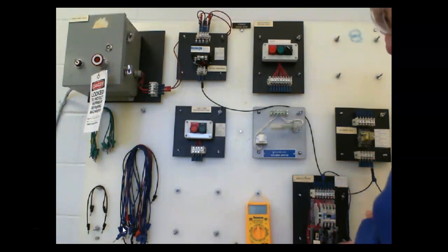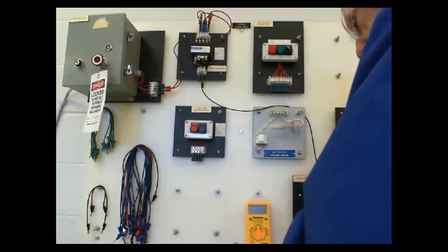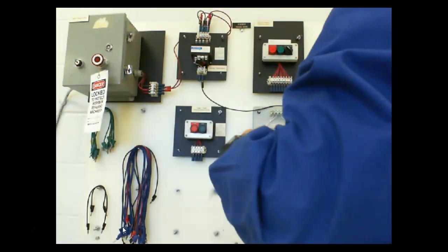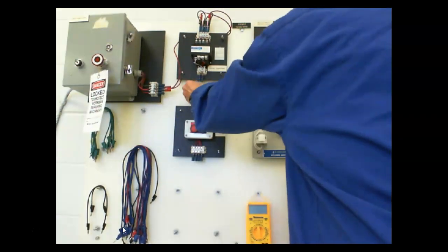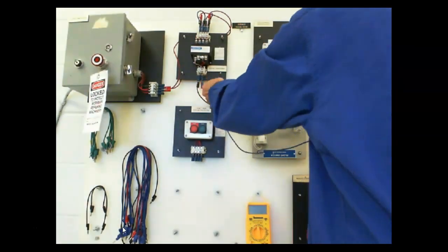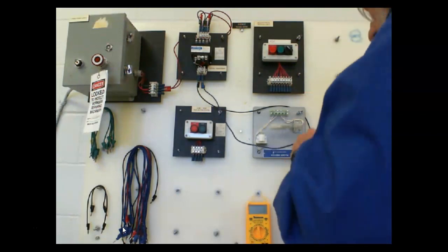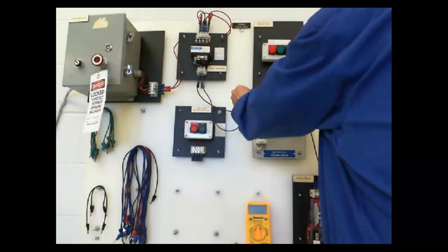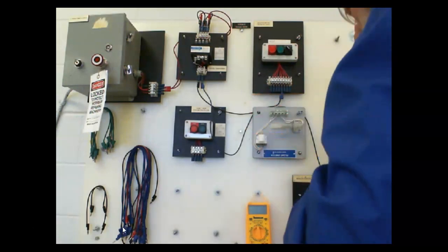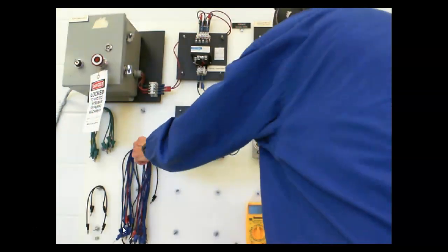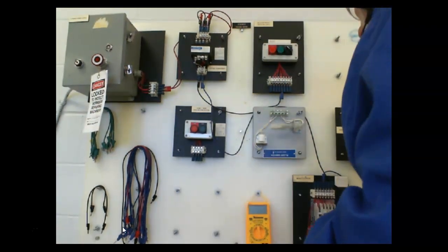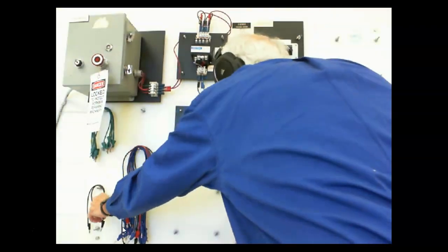That means the L2 side works. It's only supposed to go 2 places. My fuse side should go to 5 on my selector switch. It should also jump to 7 on my selector switch.